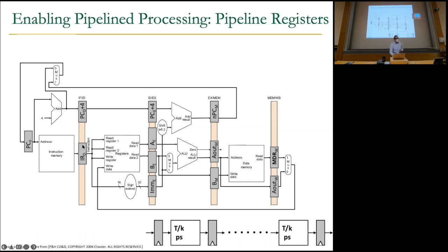In the next cycle, this instruction is going to be decoded, and it will access the register file. That's that stage, very similar to what we have done earlier. While this is happening, PC+4 is being fetched, because PC+4 was incremented while this instruction that you're decoding was here in the previous cycle. After it gets decoded, you put some signals over here. You also read the register file, put the register values over here, and put the immediate over here. So the pipeline register keeps growing, as you can see.